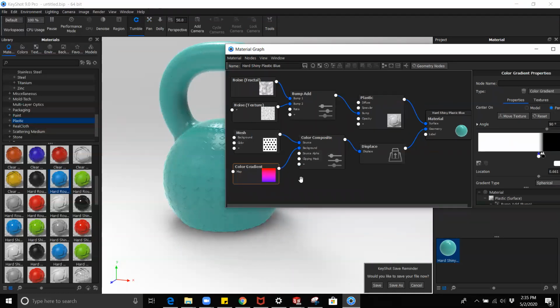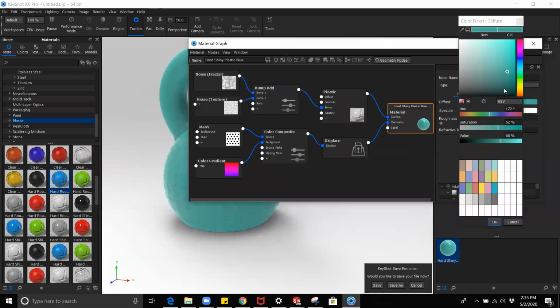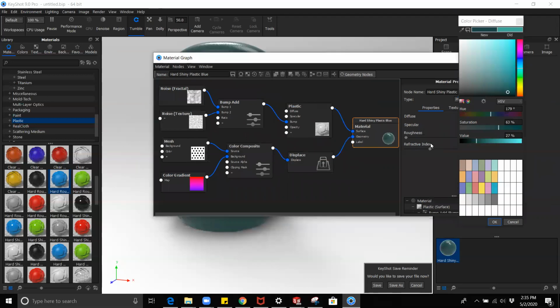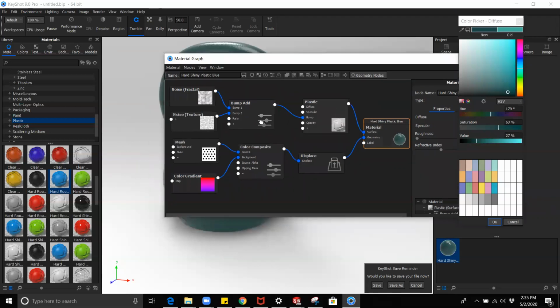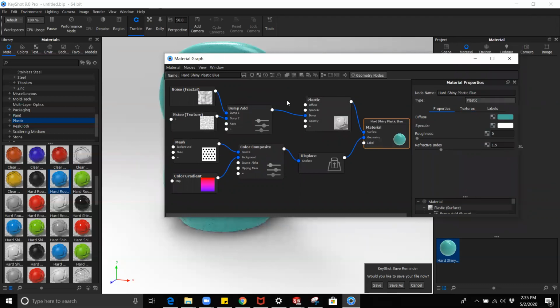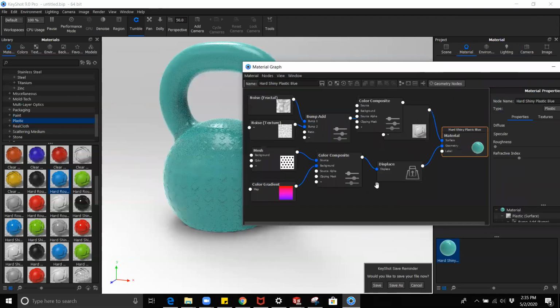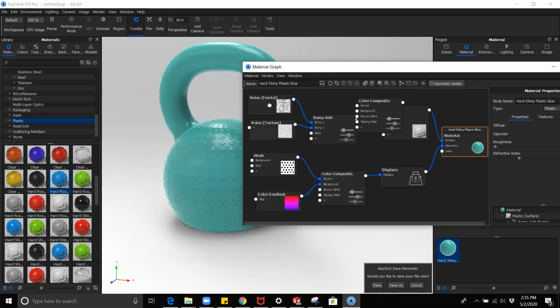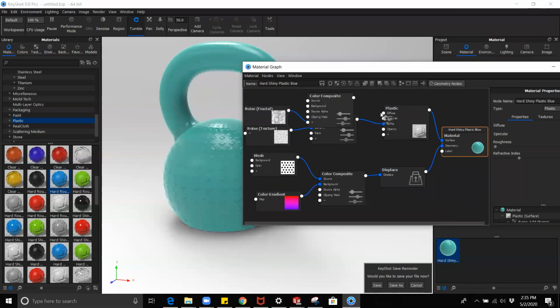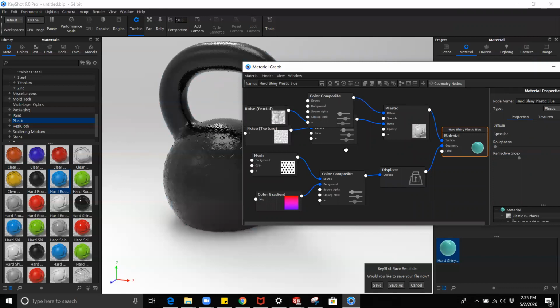Now, what about the color? Let's say that I want to add a gradient. Like I just don't want this to be blue. Let's say maybe I want a different color, but I want two colors, right? So what I could do here as well is, for example, use another utility, another color composite, attach it to diffuse. In this case, it's completely black just because there's no color.